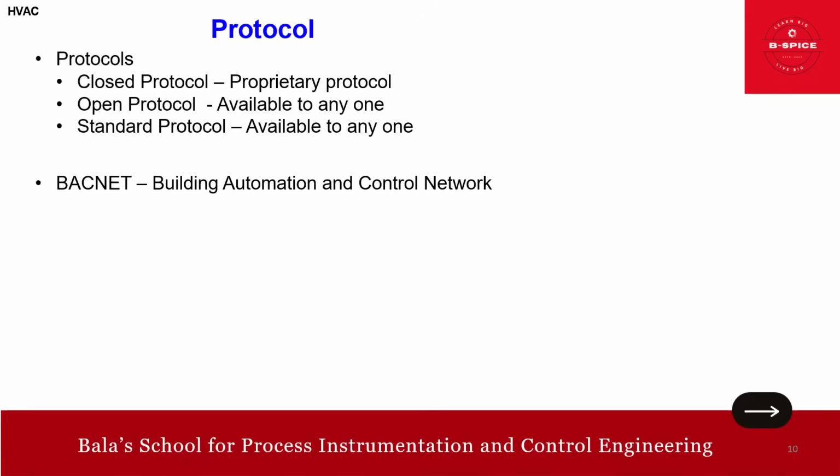Okay. So when we talk about BACnet, friends, basically it's a communication protocol designed for building automation and control systems. Maybe we'll talk about features. Features in the sense of interoperability: it allows devices from different manufacturers to communicate, simplifying system integration and maintenance. Then data exchange: it enables the exchange of crucial data such as temperature, facilitating efficient HVAC operation and optimization.